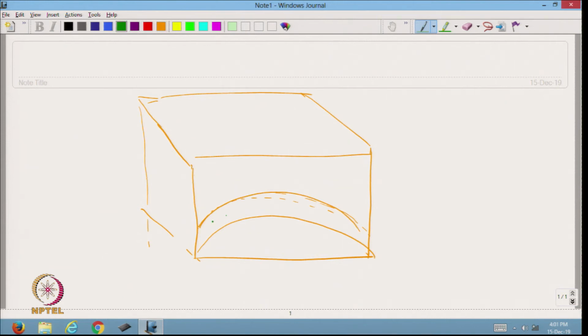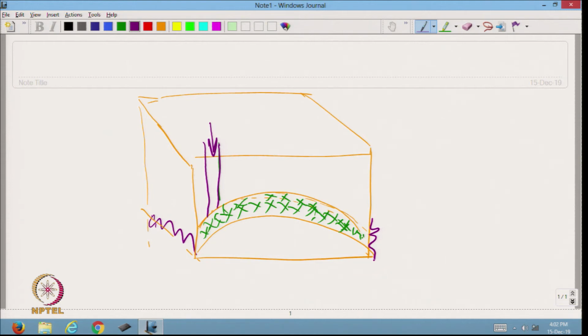Here inside we have the reinforcing material. It may be textile fabric, also nonwoven, and there will be one opening for resin injection. Resin is injected here at high pressure, and from the side there will be sealing and everything, and resin is injected at high pressure.